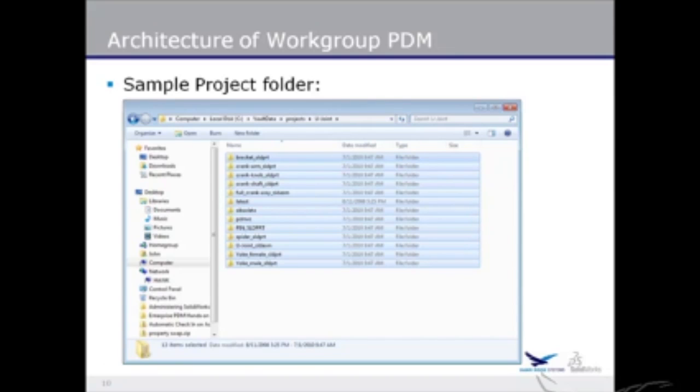You're also going to have three folders in addition to that. You're going to have a folder called latest, and there is an option in the Workgroup admin tool to keep an extra copy of the latest revision of every file. It's for things like corruption scares and things like that. If you're keeping an extra copy of the latest version of every file, they get stored in that latest folder. They don't get stored where the normal files get stored, again, because of fears of corruption and stuff like that.